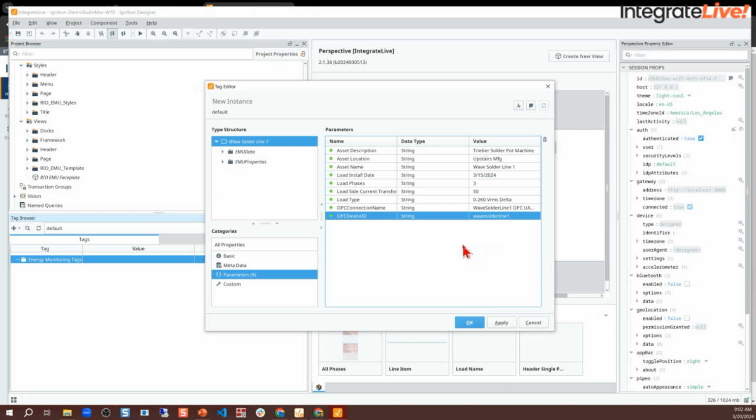Yeah, only to mention that, you probably heard recently over the past several years of this notion of the UNS, Unified Namespace, and this is an element of that. We're actually creating an asset. Now we're modeling this machine with all of its data parameters, but giving it a lot of asset information that could be useful once we get this done, if we maybe want to send it to a data scientist or whatever, rather than just setting up a bunch of process values. We're actually setting up a modeled asset. So we're modeling the wave solder machine with these UDTs, with all of these parameters in there, so it explains what the load is.